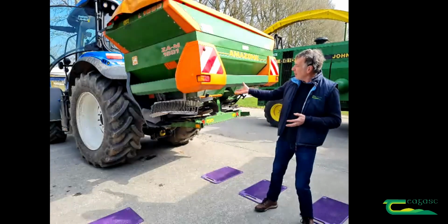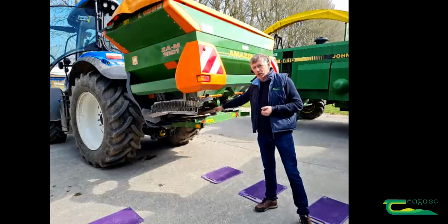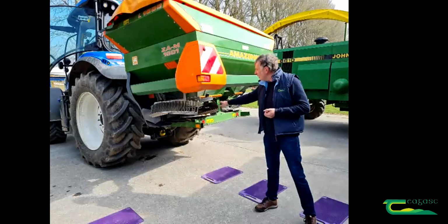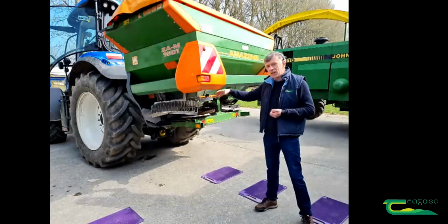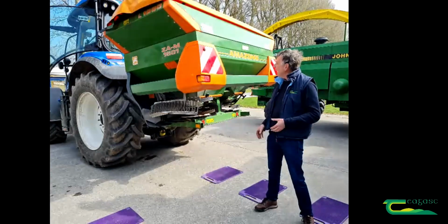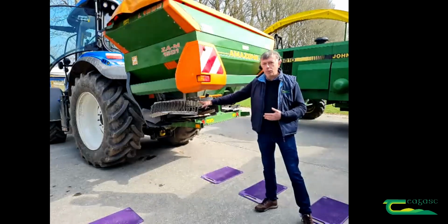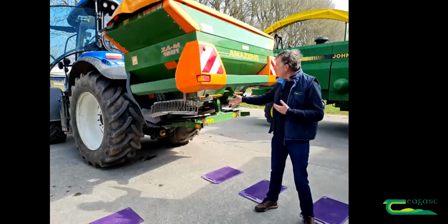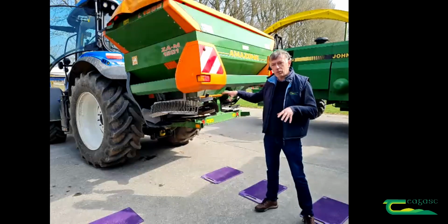So the various manufacturers have different ways of doing this. On some you'll have different discs put on the spreader for a headland run. On some you'll have different vanes. In other spreaders, you actually change the direction of rotation of the discs because it then spreads off the back of the vane, which is a different shape. On some you might actually tilt the spreader to one side. Others will use a trimmer or deflector like this. And some may slow down the disc speed on one side. So there are all sorts of different combinations.